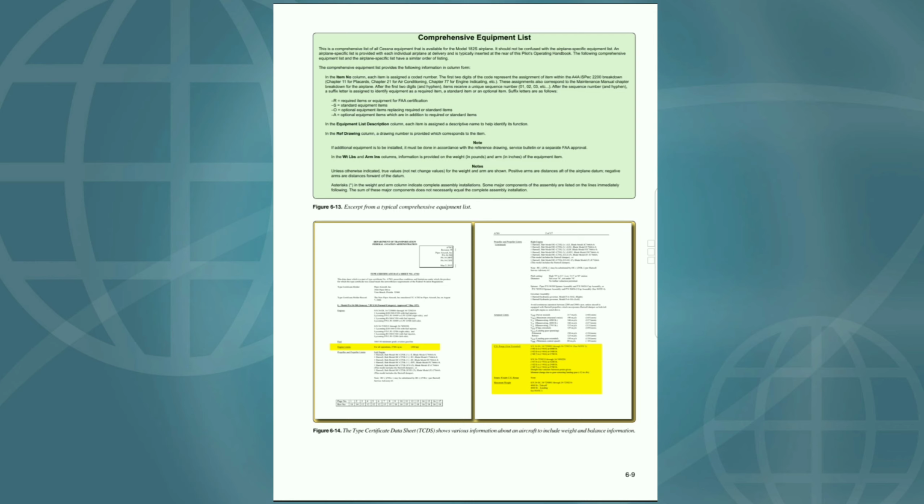S/N 34-E4, 34-7250001 through 34-7250214. See Note 3. Plus 86.4 to plus 94.6 at 4,000 pounds. Plus 82.0 to plus 94.6 at 3,400 pounds. Plus 80.7 to plus 94.6 at 2,780 pounds.